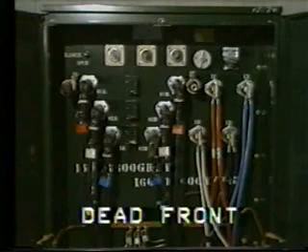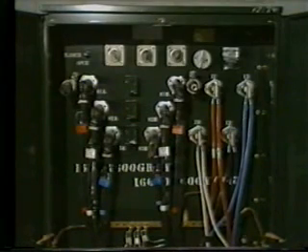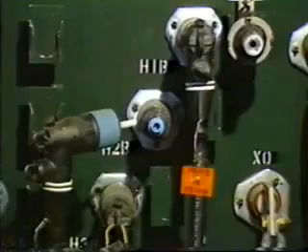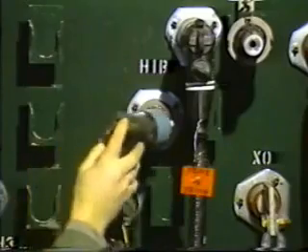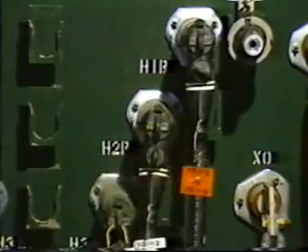In an alternative design, to ensure the safety of utility crews, a dead front arrangement is available. Here, all the high voltage equipment external to the transformer, such as incoming primary cables, must be plugged in through separable insulated connectors, or elbows. With this arrangement, no direct contact with the supply voltage is possible from the front panel.